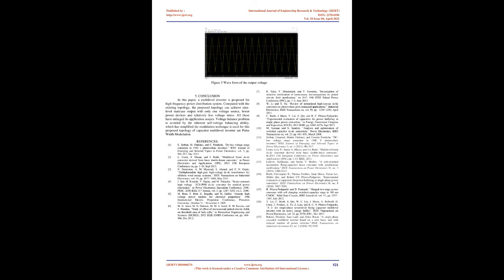Compared with the existing topologies, the proposed inverter has more voltage levels with fewer components. Lower THD of output voltage is obtained and the voltage stress on the power switches in the backstage is relatively relieved. More importantly, the inherent self-voltage balancing ability of the 2 capacitors has simplified the modulation algorithm.